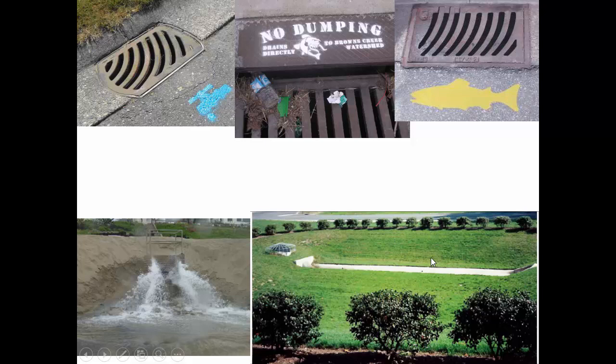And so when we assume that it's a rectangular shape or that the side slopes are vertical, it makes it a lot easier to calculate because the surface area doesn't change as the depth is going up. So the reality is if you do have tapered side slopes that extend outward, then the water depth isn't going to be as large as you otherwise would expect, because when you make the assumption of vertical side slopes, you're saying that there's this tray of water.